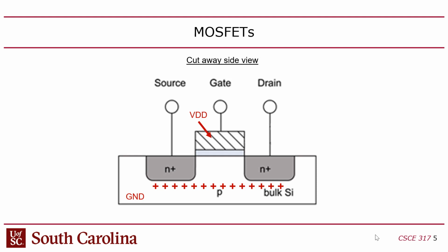and this is where it gets a little crazy, what we want to do is attract the minority carriers out of this P silicon. Remember, the P silicon is positive, so there's holes. That's the majority carrier. But there's minority carriers, which are extra electrons in there. And if you put a positive voltage on the gate, it'll create a capacitor, a capacitive effect, where you'll have charge, right?